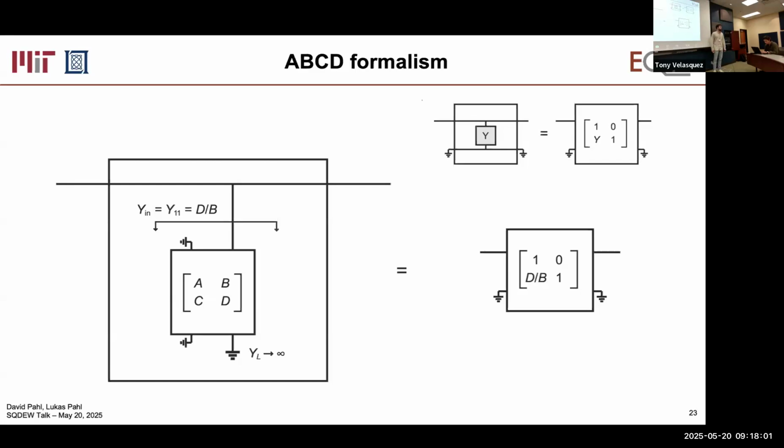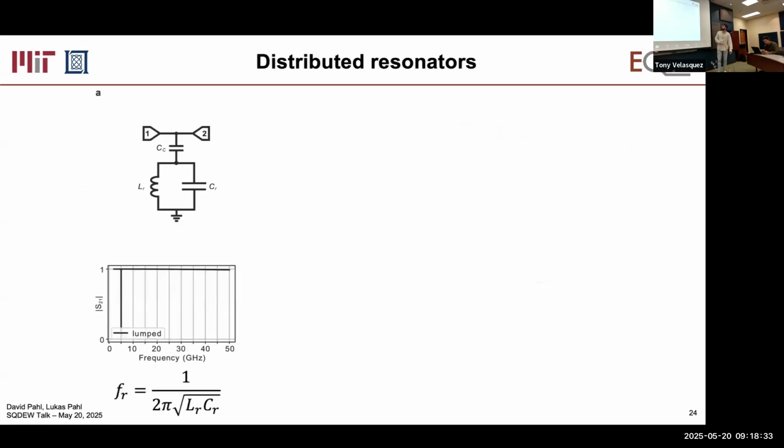Yeah. Like in practice, we'll just have a lookup table for this ABCD matrix? Or should it be obvious to me why these transformations hold? Yeah, I'm not going through them in detail because it's just some algebra you can do. There's that book, Pozar, it's all in there, right? And in fact, there is a lookup table in there. And I've compressed it here. So these are the important ones. These are the only ones we'll need to design all the circuits that I, for instance, have designed.